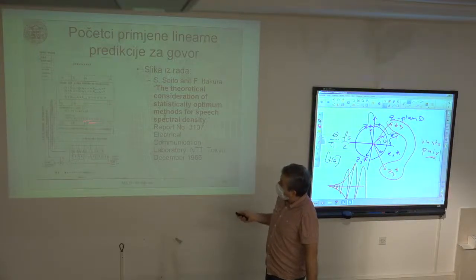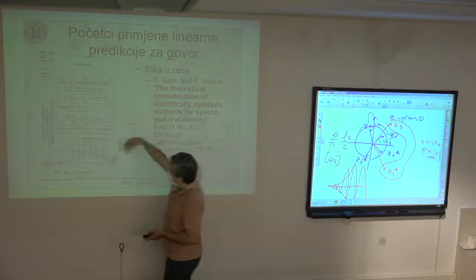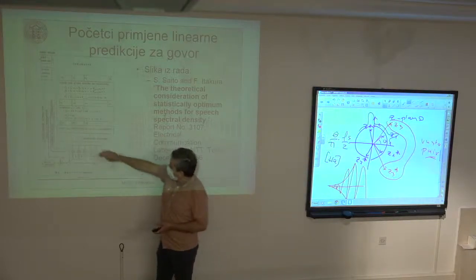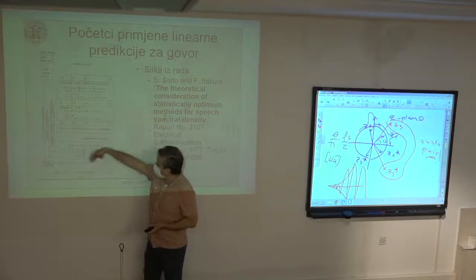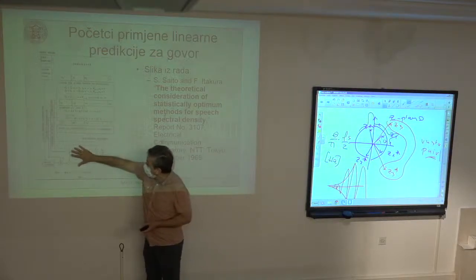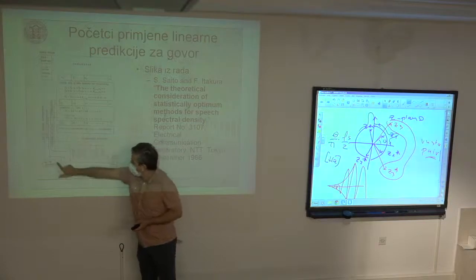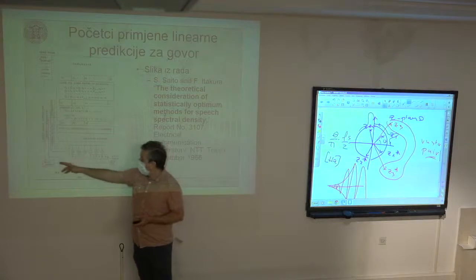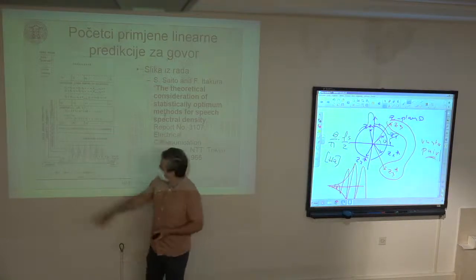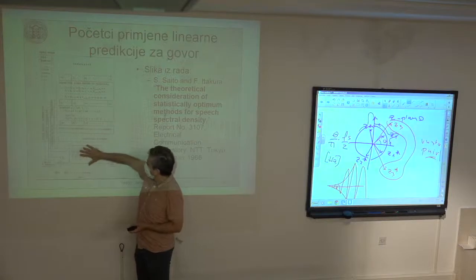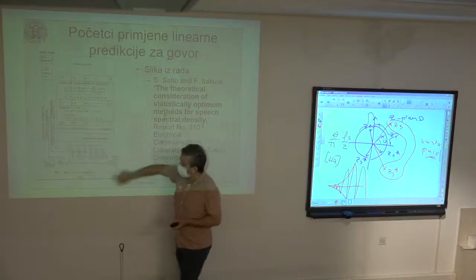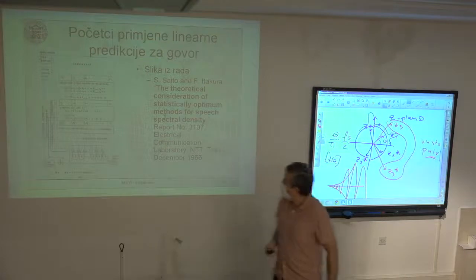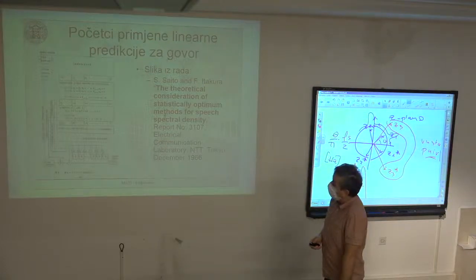So they have introduced this iterative algorithm for finding the optimal solution. And once you have this optimal solution, you simply plug these coefficients into the reconstruction filter. This here is the reconstruction filter. Here is this excitation source. And if I pass either unvoiced, so white noise, or a periodic sequence through this reconstruction filter, I would get something that is very close to the original speech signal.